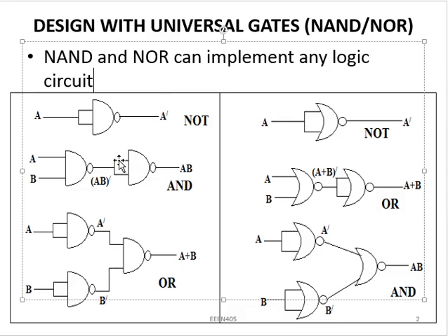And if we want to implement AND gates using these NAND gates, all we need to do is to use 2 input NAND gates, deliver our 2 inputs A and B through it. We know we are going to have AB all complemented, and this is delivered to the input of the next NAND gate, and it will complement it again, that is AB complement complemented. In double negation, we know they will cancel out each other, therefore we have AB at the end of the day.